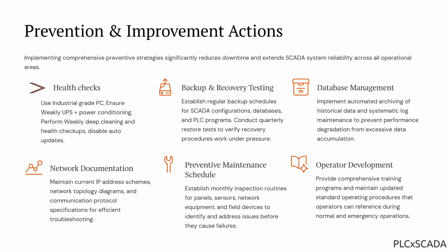For network infrastructure, use industrial switches instead of cost-effective office switches. Label all the cables and maintain a network diagram. Use shielded Ethernet cables. Keep a separate LAN or WAN for the SCADA. Keep the IP address scheme updated.